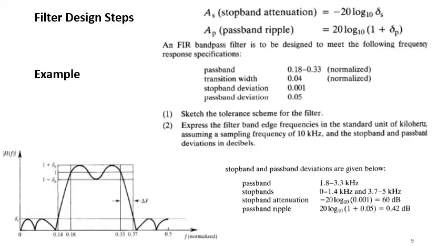The stop band and pass band deviation may be expressed as ordinary numbers, or they can also be expressed in decibels. In decibels, you understand, you're not new to this one, you just take the log and multiply by 10. For the squared case, we multiply by 20.